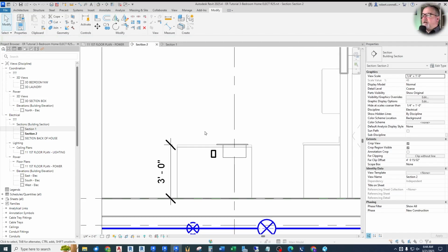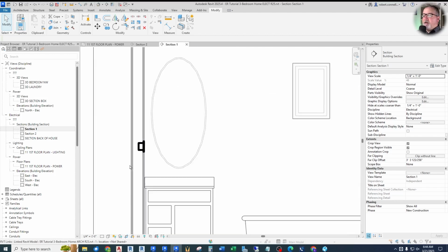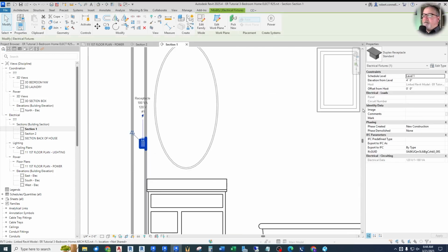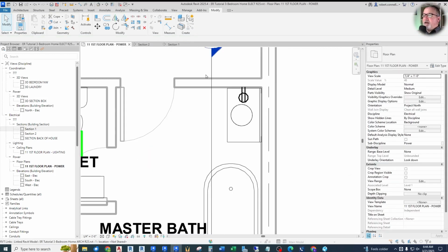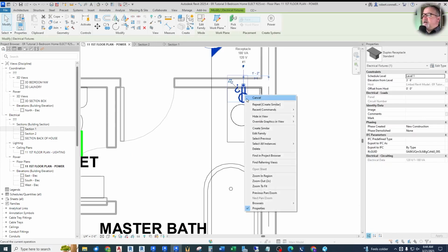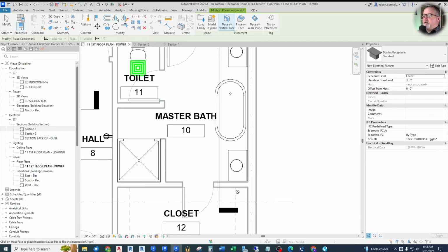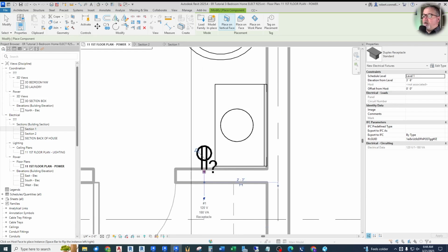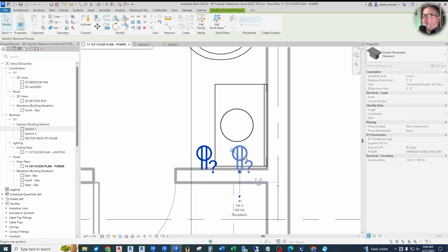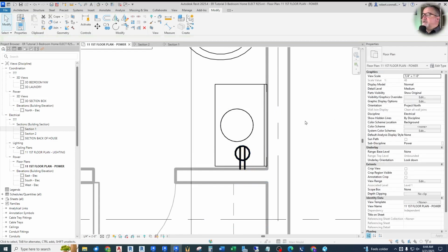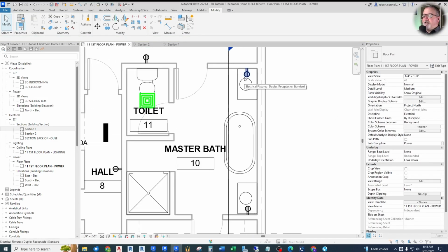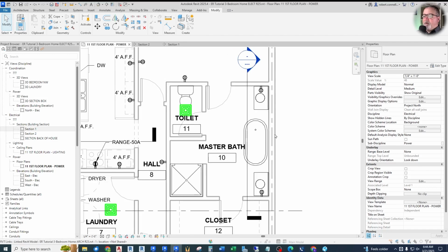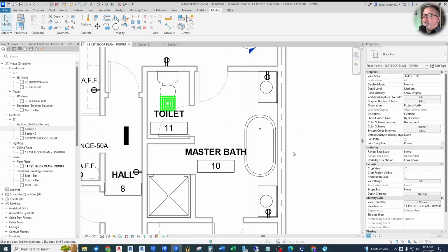Let's check that height. That's the kitchen. So there. Now we could put this down at the 3'6" level, and that looks a little better. So we'll do the same to the other one. Let's create similar this one, get it down on this south wall, and move it over. And it's at 3'6". We're good. Now again, this would be a GFI, GFCI type receptacle. We're going to handle that with general notes. So that is that bathroom.